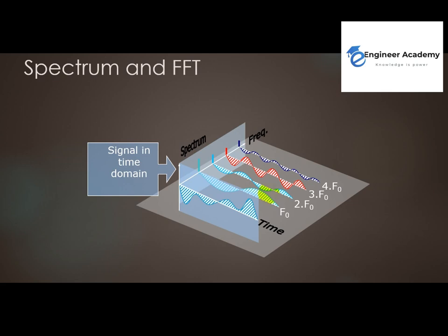Then each part produces not just one waveform, but many waveforms. Like in a bearing, we have four parts in each bearing. By considering all these parts coming together, you can't make this analysis very easily. That's why we go through the fast Fourier transform.